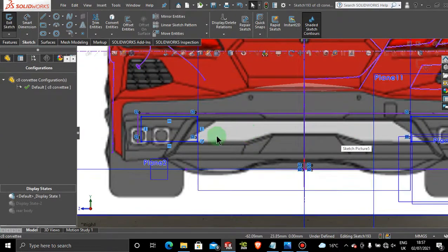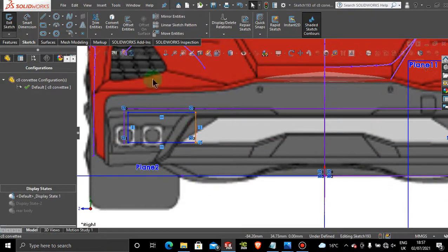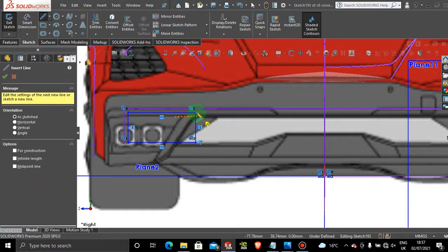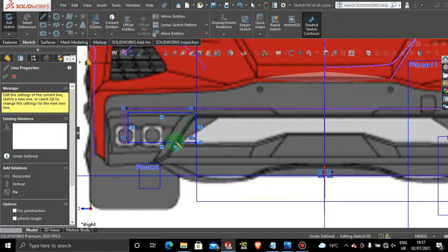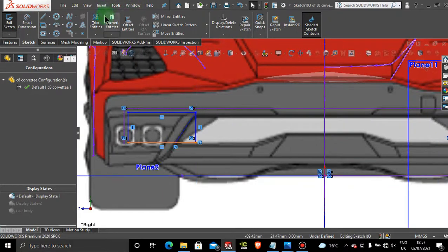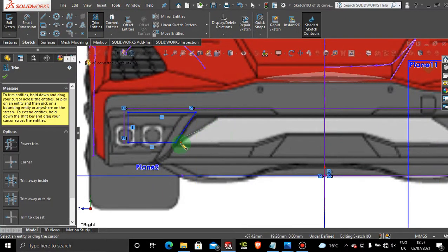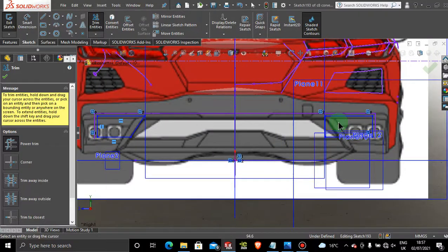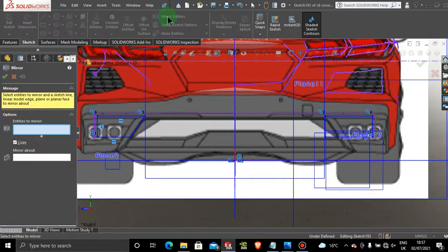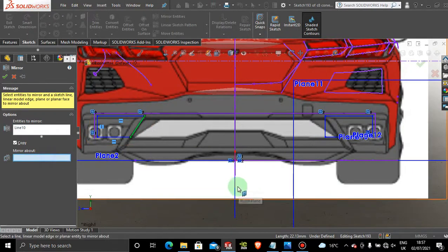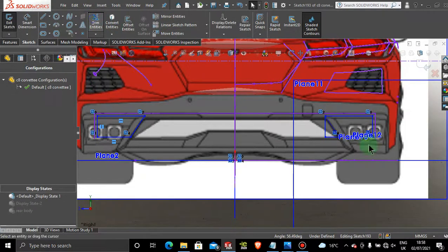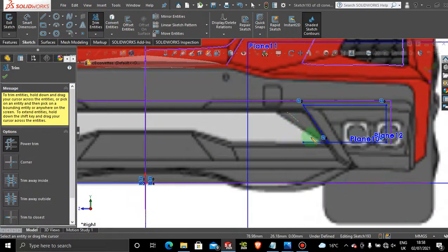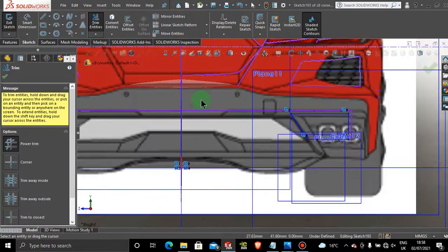and then it looks like that bracket has something like that. So let's create that. Let's bring it down somewhere parallel, and let's choose this corner here. All right, so let's do a mirror entities to mirror this here, and mirror about here, and then about these corner pieces. Perfect.